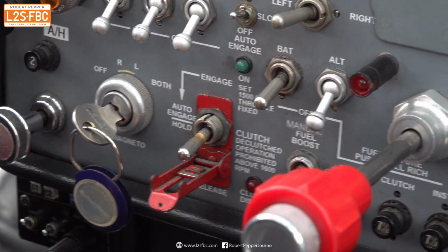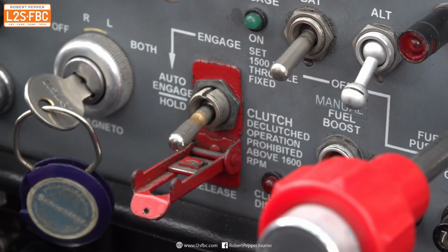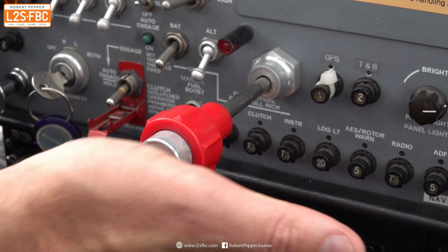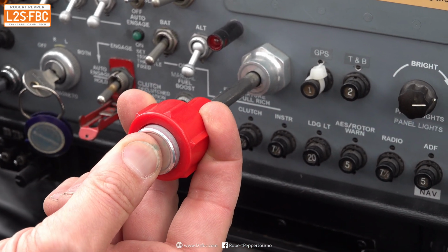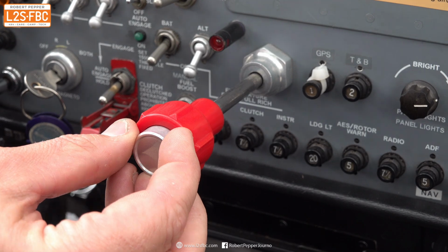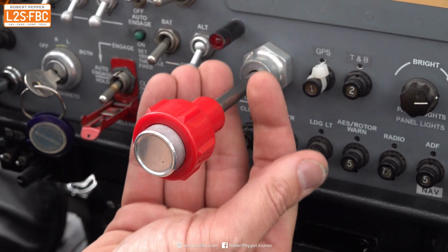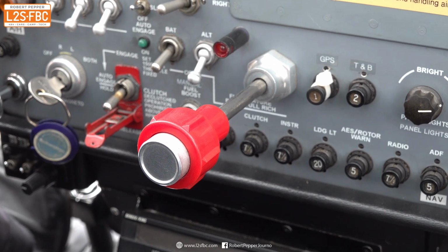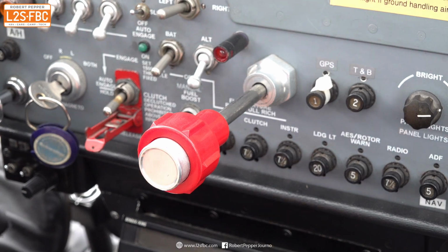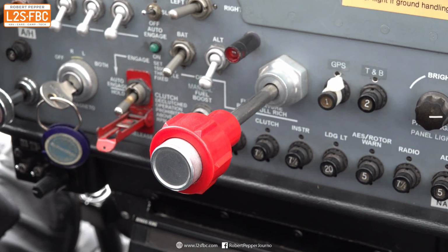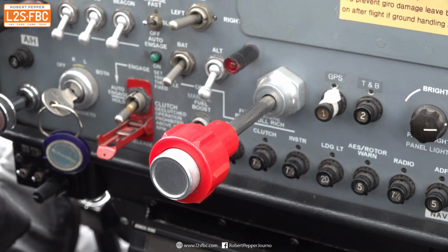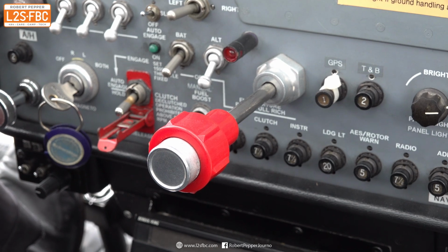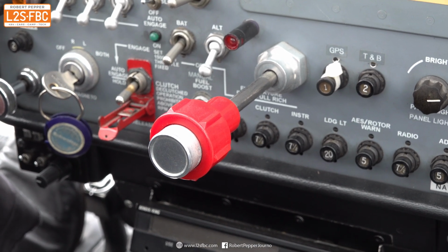Now you could say, all right, we need more than just a spark. We need something to burn, to set on fire, which is the mixture control, this big red push button. Once the engine is running, we're not going to touch it, but this is actually the cut-off position, so no fuel flows into the engine. So maximum lean? Yes, literally this is cut off. There's no fuel. It's roughly equivalent to a choke on older cars, but now it's all done electronically. Keep in mind that when you pull it all the way out like it is now, there is absolutely zero fuel running into the engine.